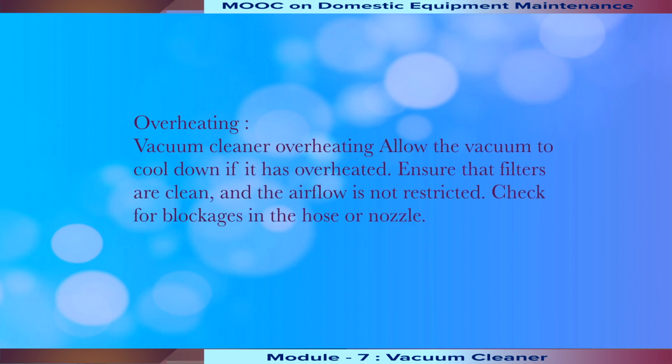Overheating. Allow the vacuum to cool down if it has overheated. Ensure that filters are clean and the airflow is not restricted. Check for blockages in the nozzle or hose.